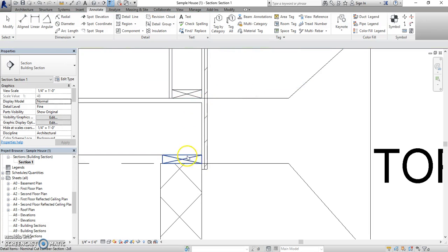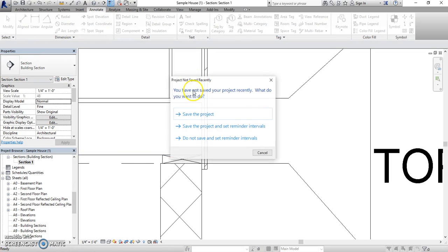We also need a rim board, something that kind of binds the ends of all these joists that are spanning, running in this direction. So if we were to look at the end of this floor framing through this wall, we would just see the ends of a 2x10 every 16 inches. Well, we need something to close that in. So we have 2x10 joists. We're going to go get a 2x10 rim board component.